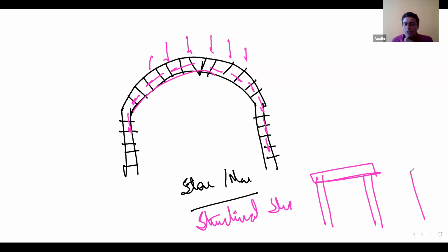You provide very closely spaced columns so that the beams that you put on top of them, the stone beams or masonry beams, develop very small bending and shear because of closely spaced columns, and then the load can be easily transferred. So either you see closely spaced columns with deeper beams in stone construction, or you see the use of arches.